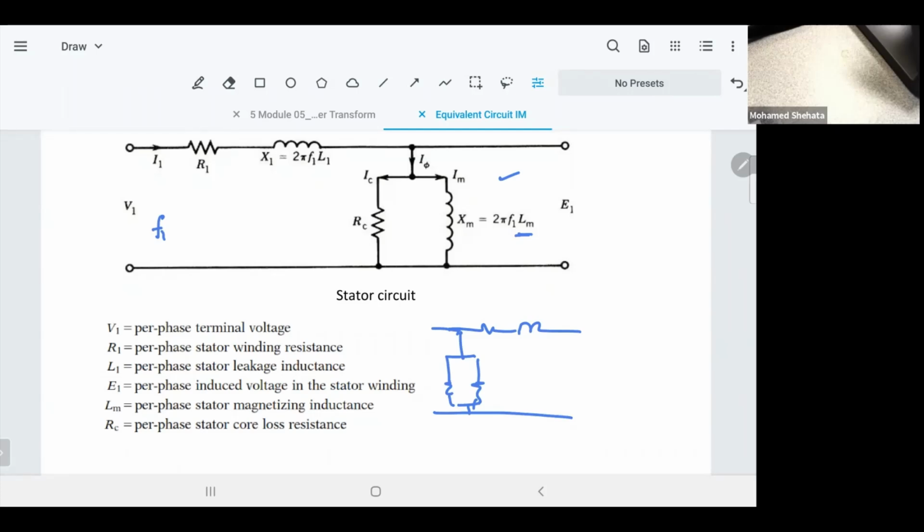Reluctance will be different. Exactly. When you don't have an air gap, you don't have this reluctance, but the reluctance of the air gap is bigger, right? As you know, what happens is that I phi is responsible for all the magnetizing and the core loss. It's in the induction motor much greater than that in the transformer.